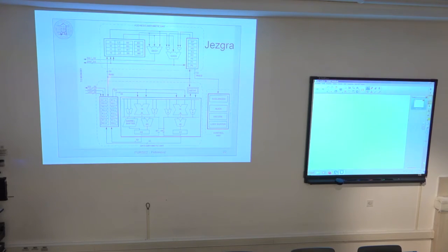And in the core, it can only be written into a register file. It cannot be used directly in execution units. It must first be written into some of the registers and then used from these registers as an argument of an ALU or MAC instruction and so on. It says here there is a separate store data bus.